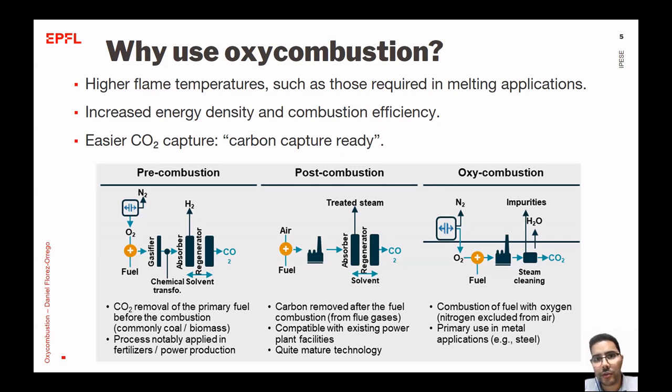We say that the oxycombustion flue gases are mainly composed of water and CO2. Then if we can condense out this water, the CO2 can be separated, treated, and then used in other applications or in permanent sequestration. If we compare oxycombustion with post-combustion carbon capture, the latter requires the use of chemical solvents that also consume a lot of steam for regenerating the solvent and releasing back the CO2.